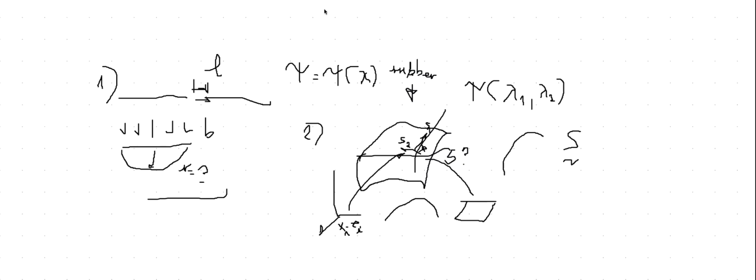I mean, it turns out you no longer need curvilinear coordinates, even if you deal with something which is a 3D space curved surface. You can always simplify computation by taking into account the local Cartesian system and then doing the computation inside this local Cartesian system. So the only trick is, how do I compute d over ds1, or whatever it is that I'm trying to compute, displacement and so on, and d over ds2.